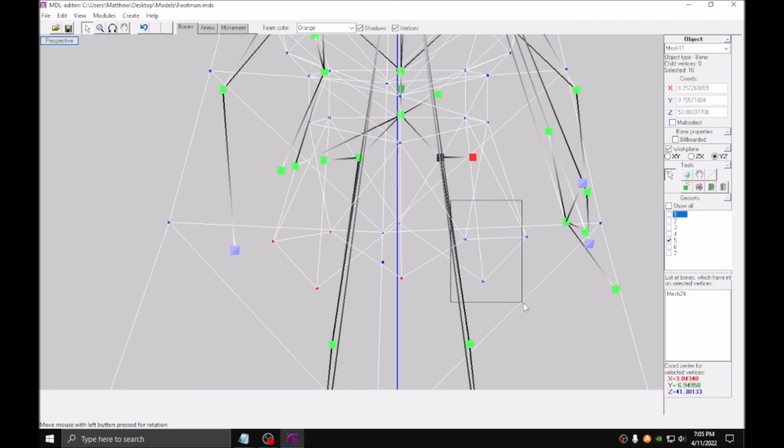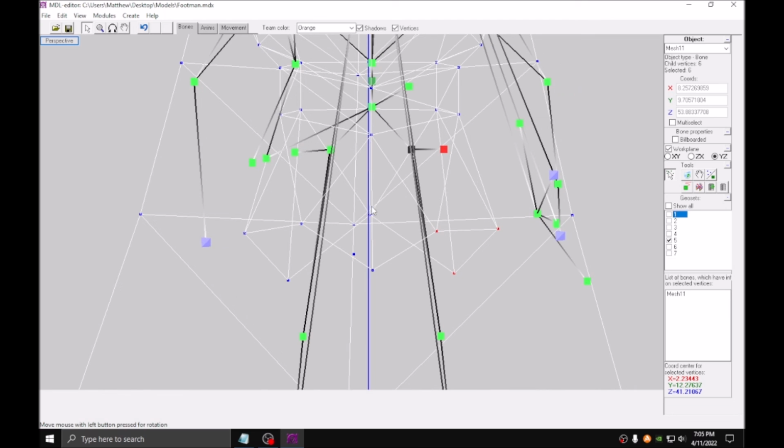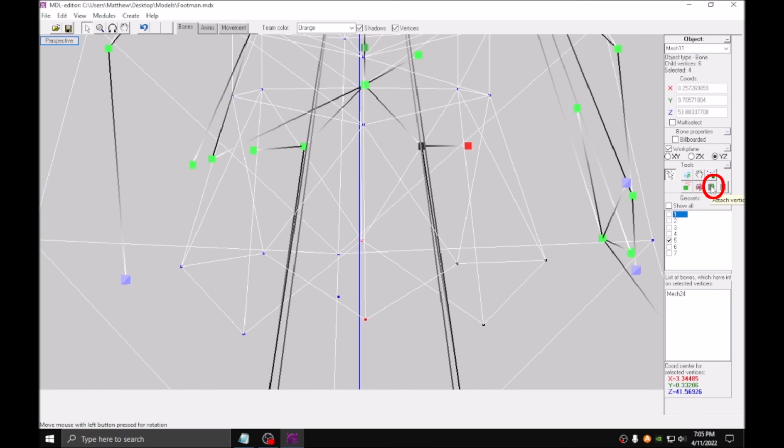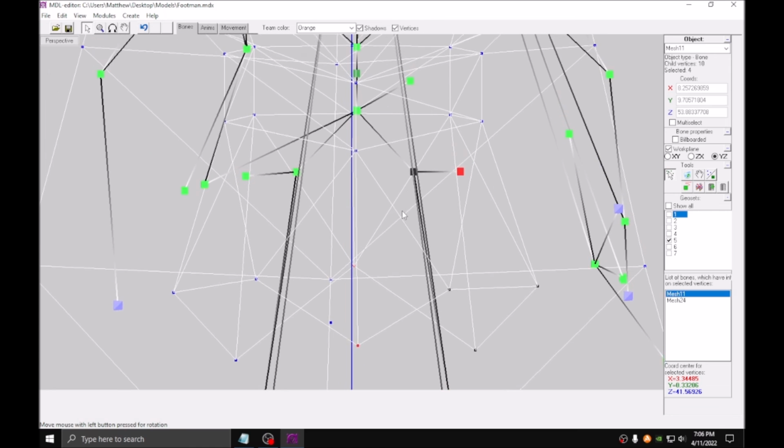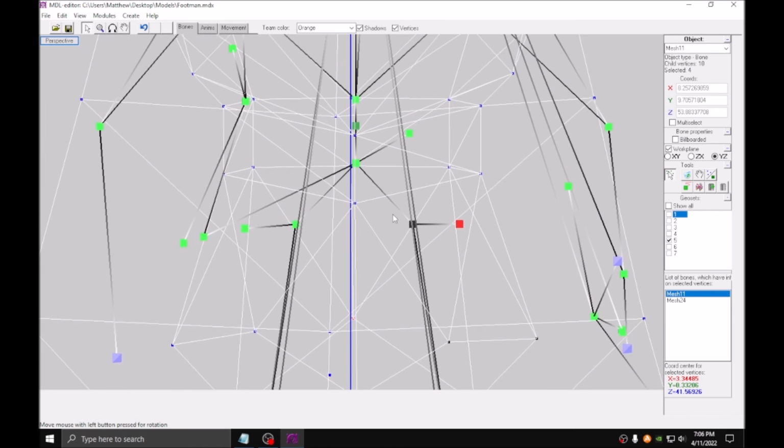And with the other leg, the same on this side, but not in the middle. We don't want to bind these solidly in the middle. Select these middle polygons here, and press this button instead, Attach Verticals to Bone. Down here we have the list of the bones that these polygons are sharing. So these will both react half and half to what each of these legs are doing. This should prevent any sharp tearing or unwanted stretching.